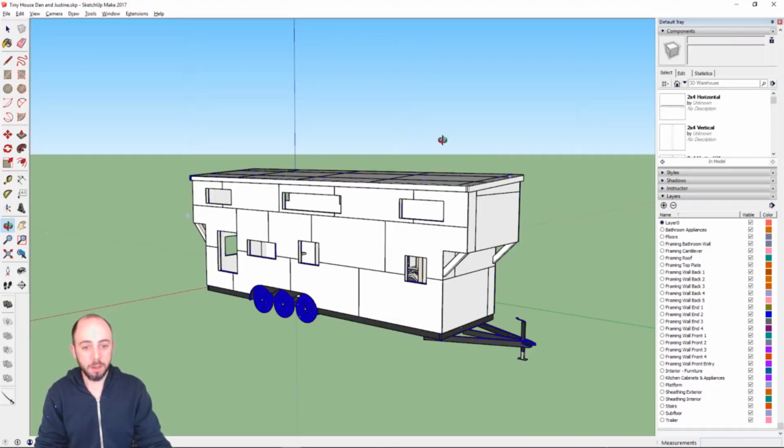I am going to take this model and create a set of sections for section drawings with dimensions for each of the wall segments. So I can literally just take those images, print them out if I want to, take them out to the workshop outside and just build those walls. And I don't have to worry about anything fitting together really. I know that it works because it works in SketchUp, and I can just build them individually and then raise them all in a single day.